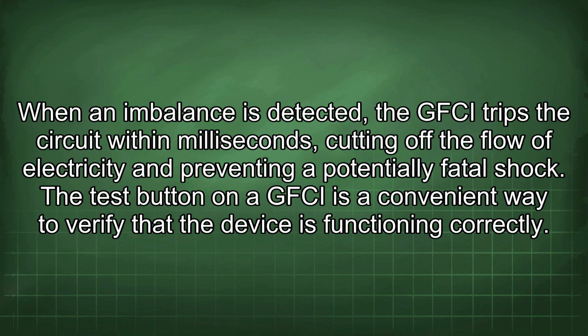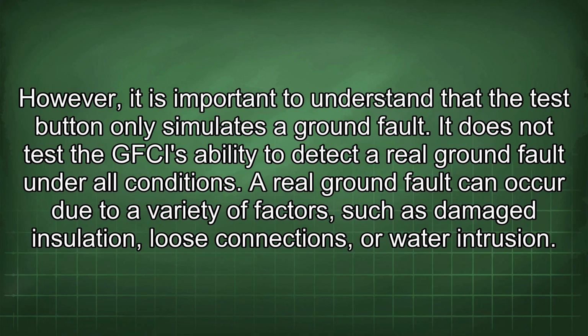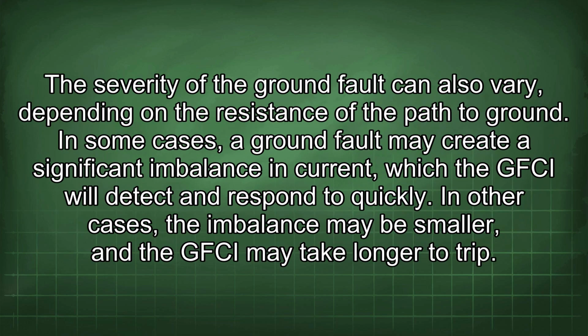The test button on a GFCI is a convenient way to verify that the device is functioning correctly. However, it is important to understand that the test button only simulates a ground fault. It does not test the GFCI's ability to detect a real ground fault under all conditions. A real ground fault can occur due to a variety of factors such as damaged insulation, loose connections, or water intrusion. The severity of the ground fault can also vary, depending on the resistance of the path to ground.